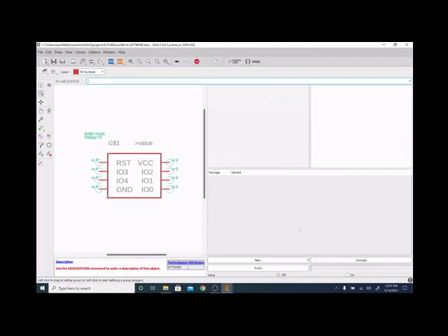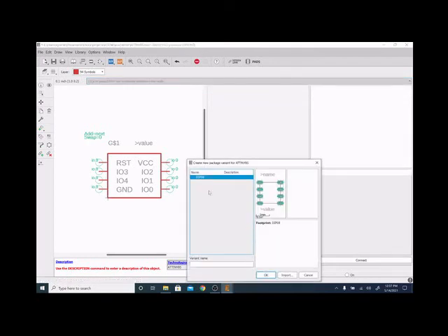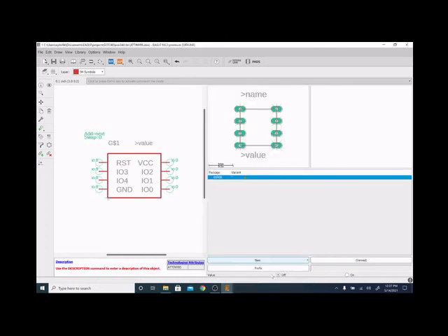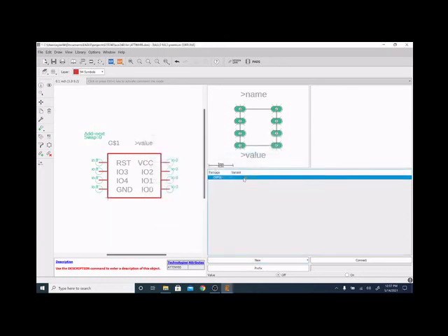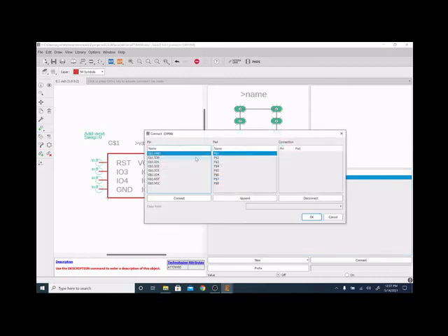But now we need to add a new footprint. So we're going to go here. We're going to say we want to add from the local package. And look, we only have one that we can add. So we're going to hit OK. And that pulls that up there nice and tight for us. But you can see there's a little warning here. If we double click, it'll bring it up for us. But what's happening is we need to connect the pins so they correspond with each other.